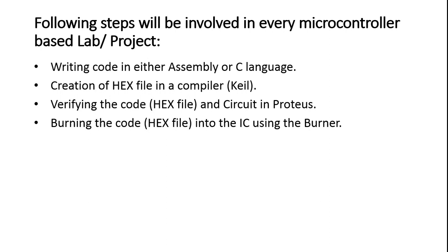And then the final step, the last step, is burning the code into the IC using the burner. This is for the hardware part, since we are not actually burning the IC this time around. So we will be burning the code in Proteus. So you will have to load the hex file.